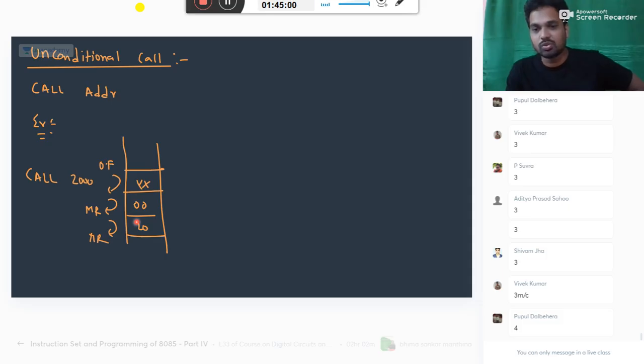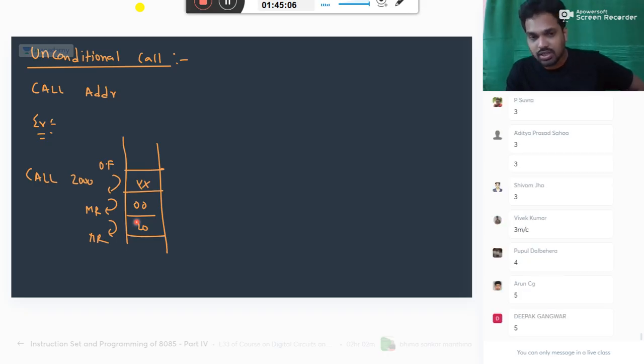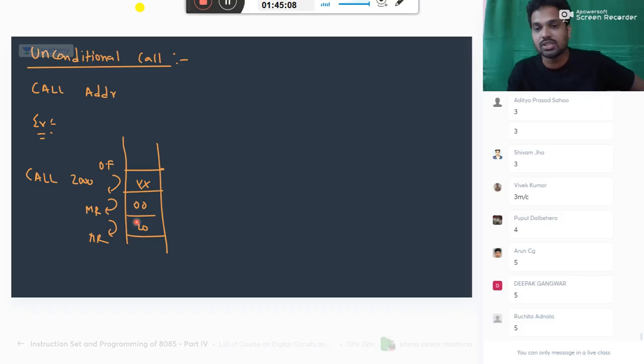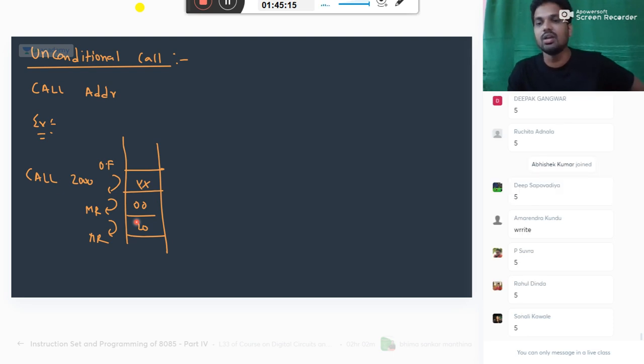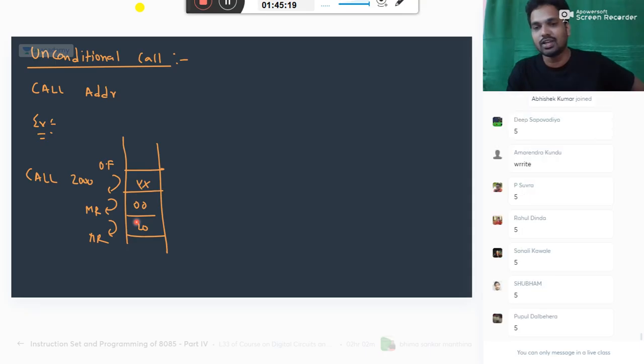Program counter is 16-bit, it is to be stored into the stack. That requires 2 extra machine cycles. Total 5 machine cycles. Very good. It requires 5 machine cycles. Okay, so that is how you need to remember some things at least.